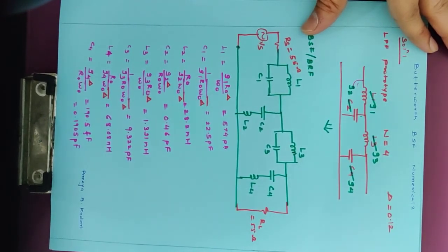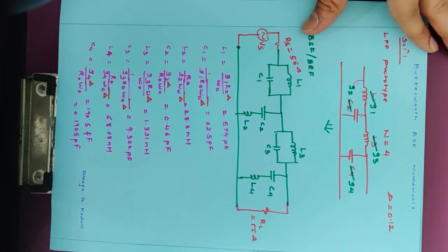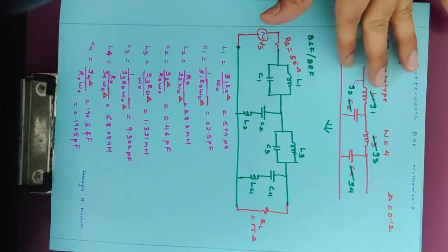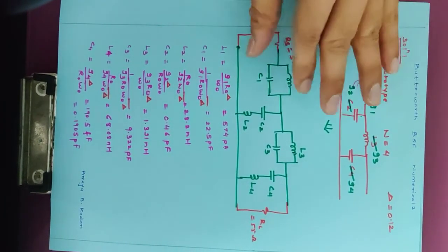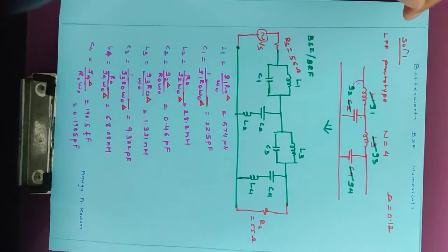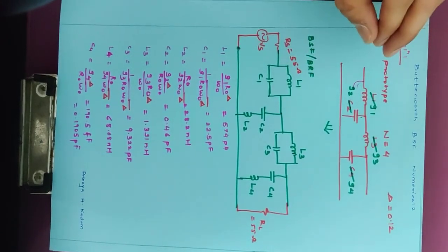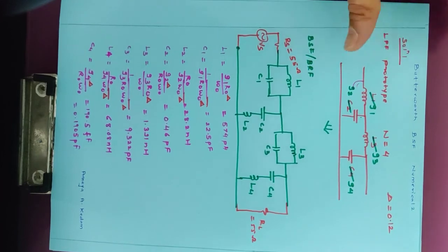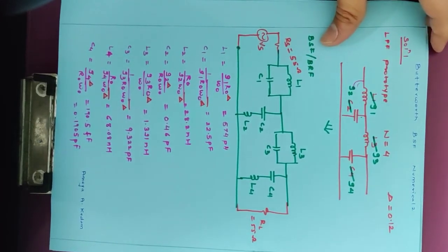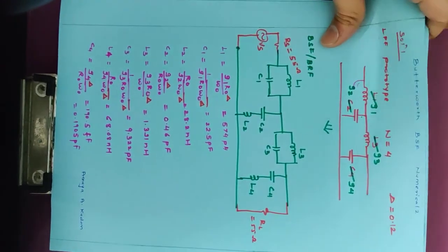We can directly design the low pass filter, but for band pass and band stop filter, one has to design first of all the low pass filter prototype, and then one has to transform it into the band stop filter accordingly. So that is all about the Butterworth filters.